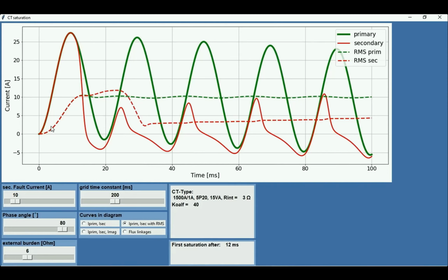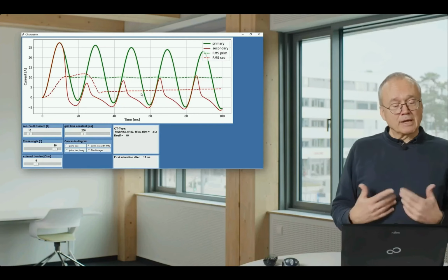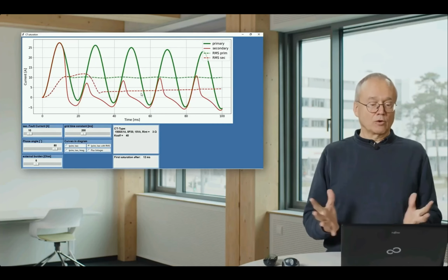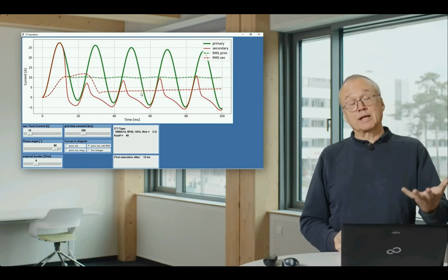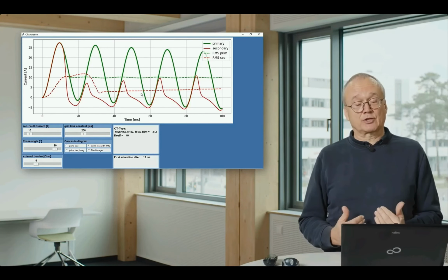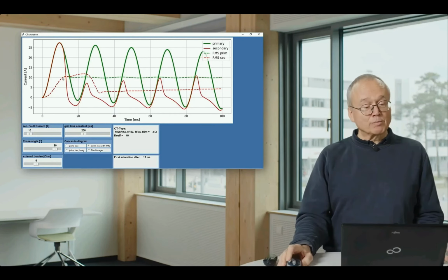And if we look at that result based on what our protection relay measures, that looks really strange. So it goes up. At the beginning, it measures really something around 10 amps, but then it goes down, and from this disturbed quantity, it measures something like 4 amp, 5 amp. And what would that mean? Imagine you could have a setting maybe in our protection relay of 5 amp. You have 10 amp short circuit current. You would expect tripping.